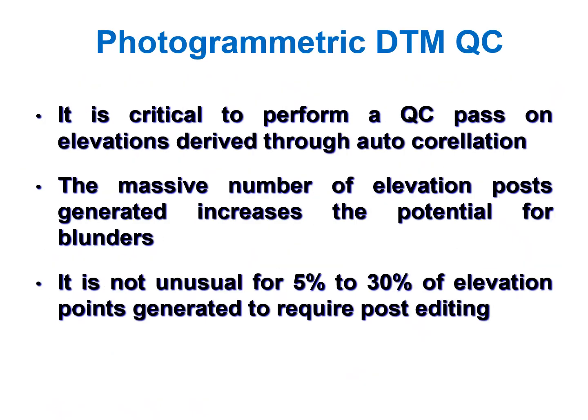Photogrammetric digital terrain model, QC. It is critical to perform a QC pass on elevations derived through autocorrelation. The massive number of elevation posts generated increases the potential for blunders. It is not unusual for 5 to 30% of elevation points generated to require post-editing.